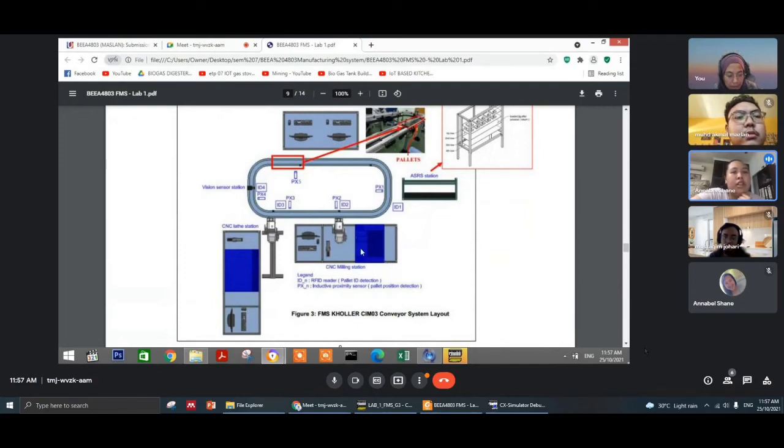After the process finishes, the robot arm will pick up the finished nylon workpiece and put it on the jig, and this will cause the inductive proximity sensor to sense the nylon and open the stopper. After that, the workpiece or jig will move forward to another station.